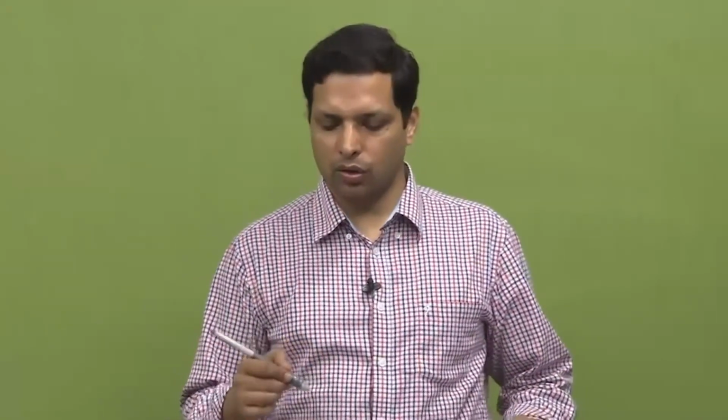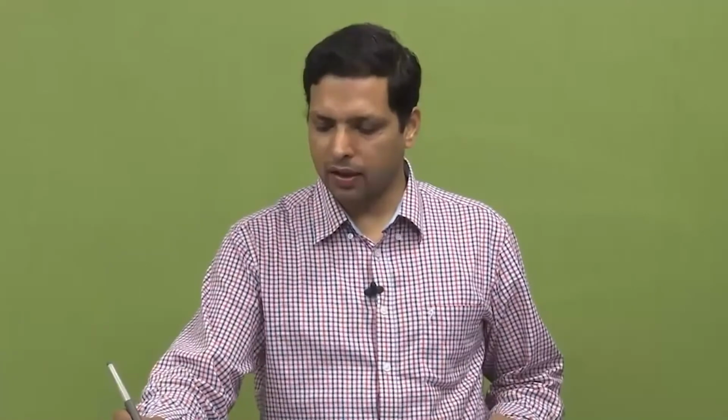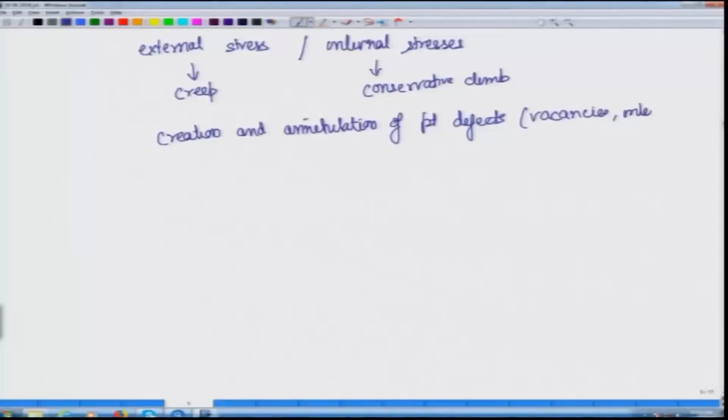So, their concentration must also change for the dislocation to climb, and therefore, creation and annihilation of point defects, vacancies, interstitials, must change for climb to take place.